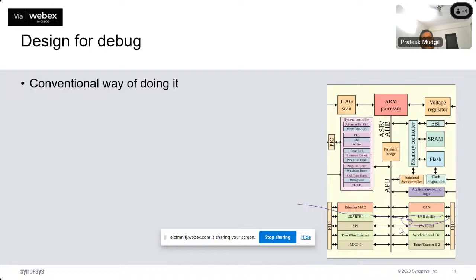So you see, the industry changed in the last 10 years, where we started from the freedom of doing our debug hooks inside the blocks, whereas now the IPs are coming from vendors, right? And now the freedom of the SoC developer is gone, because we are not allowed to touch the internal IP. Let us say we are working in company A, and buy an IP from company B, and suddenly we have a requirement for a debug hook at SoC level, and we decide to add some RTL logic inside the block given by vendor B.